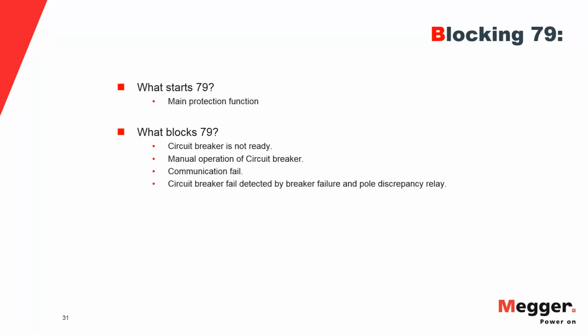And it can even detect, depending on how you program it, discrepancies between the status of the circuit breaker signal fed to the relay and the remote instance of that same signal that's being read by the SCADA function. Things like that can, because you have an ambiguous state, prompt the blocking of the recloser operation.